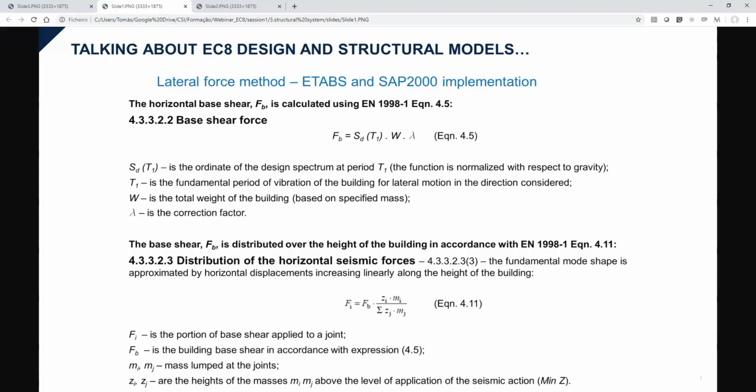Since classification as a wall or frame system, even if dual, implies a 50% contribution from one of these systems, if we used a global calculation system, the secondary elements might absorb base forces in a way that prevents either the frames or walls from reaching a contribution higher than 50%. For the sake of consistency and doing it correctly, it seems more accurate to perform this check with the primary system. So, we will use the primary model we already know as the basis for our seismic calculation.